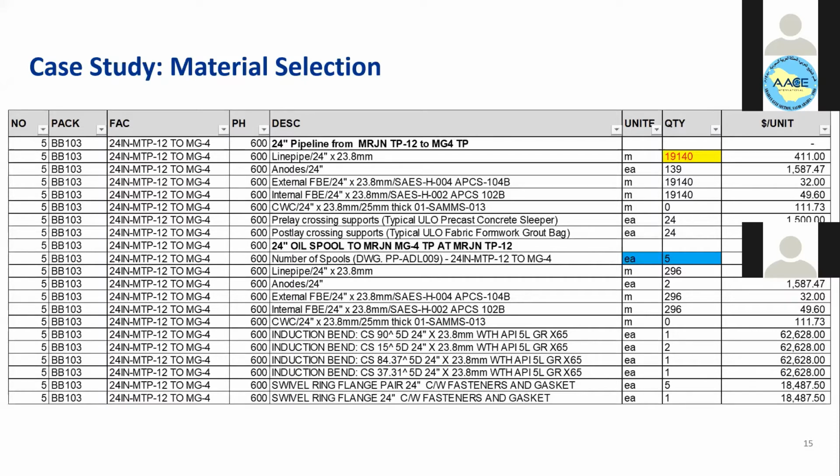In this case, once we develop the estimate, you as an estimator come up with the construction philosophy. And based on your estimate, everyone is going to rely not only on the cost that you provide, but also on the construction activity. For example, in scheduling, they will base the project schedule on your resources. I mean by resources, for example, the pipe laying barge. It's the estimator who will decide to use one vessel or two vessels, so minimizing the cost or minimizing the time.